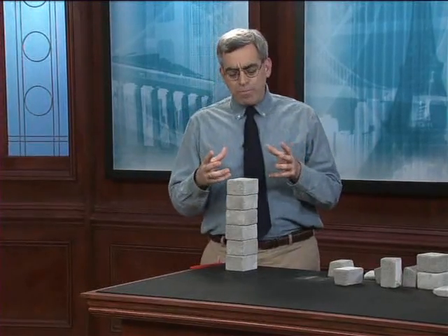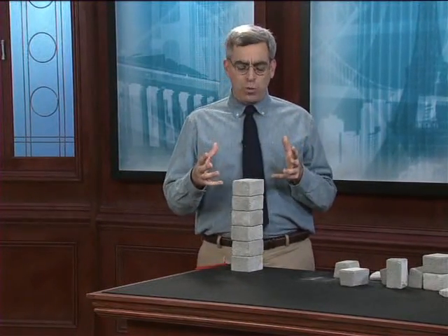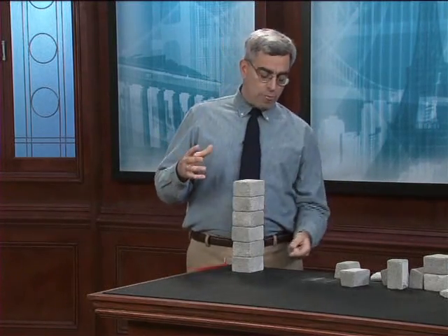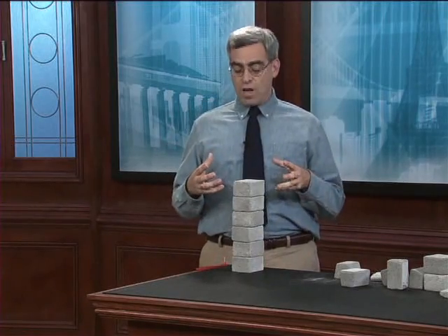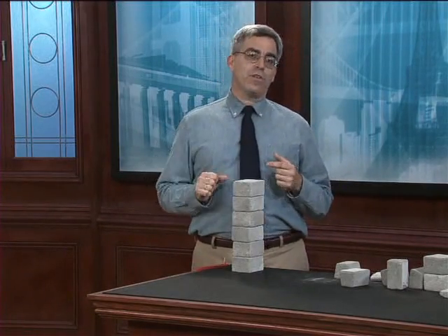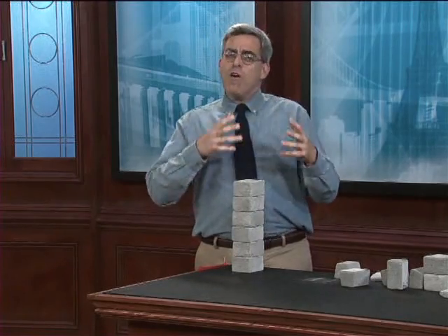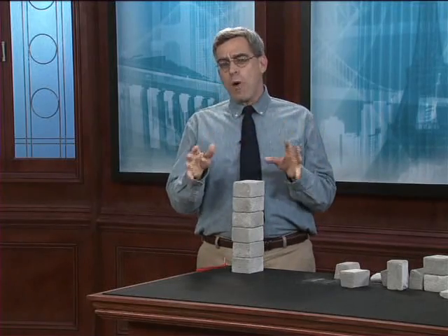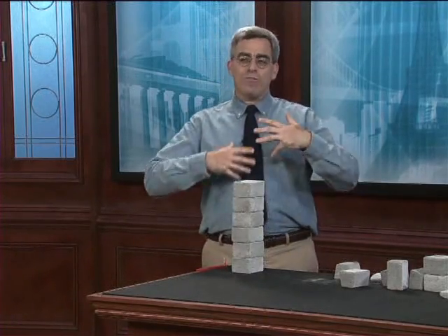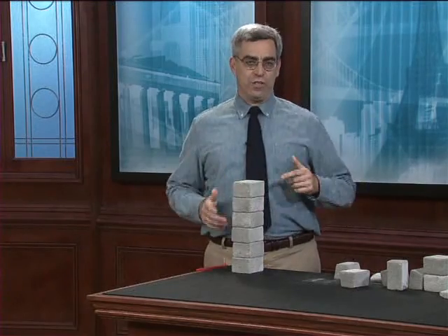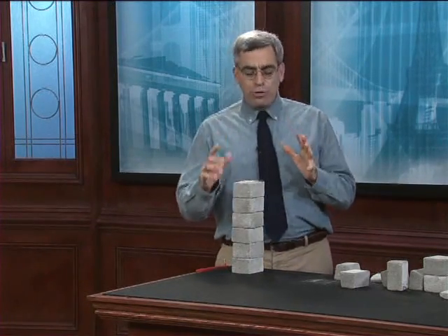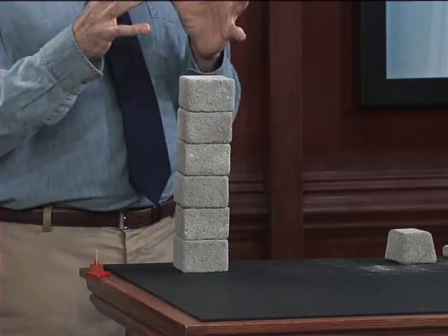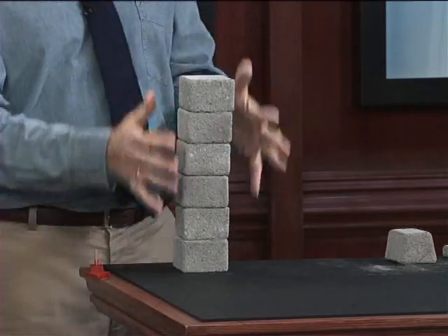Now, at this point, I could use equations of equilibrium in order to solve this problem. Write the equation of equilibrium for the sum of moments about this point, and then solve for the unknown thrust applied up here at the top, and then use that as the basis for figuring out what we might have to do in order to stabilize the column. But rather than using an equation, I'd like to actually use the model itself to talk about how equilibrium works in this situation. In this situation, where the column is just on the verge of tipping over, it's useful to think in terms of two different moments acting on this body.